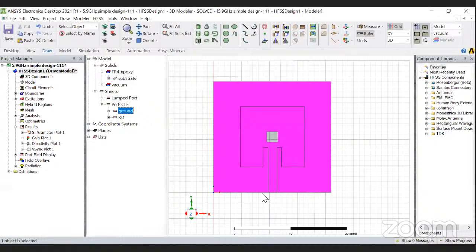So we got the gain value of 4.7, and we need to go for analysis of directivity also, the same thing. Directivity is a constant value, but here we need to check the dB value only because it's possible to get a dB value. Select the same process, the results, right click on it, create far field report and go for 3D polar plot. In the 3D polar plot, you select the directivity and select the unit function value in dB, and you get the directivity value. So just double click on the directivity.